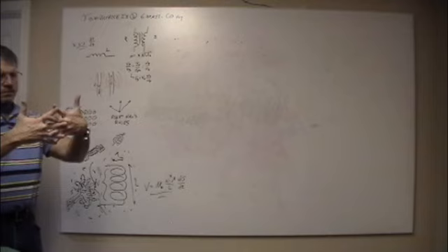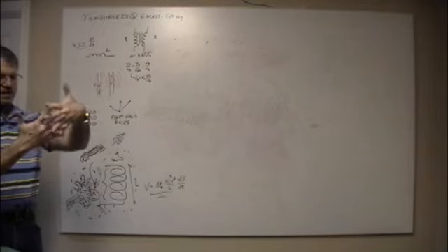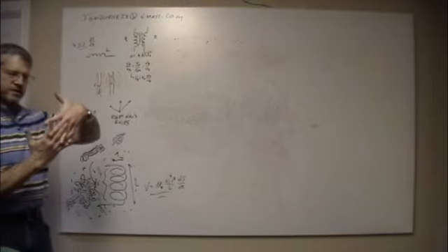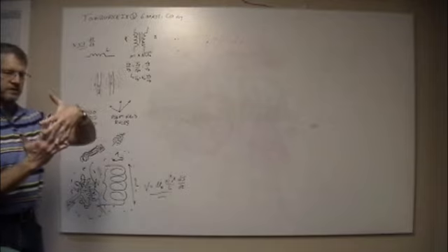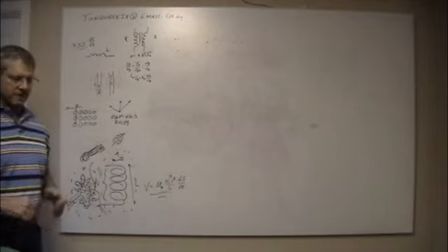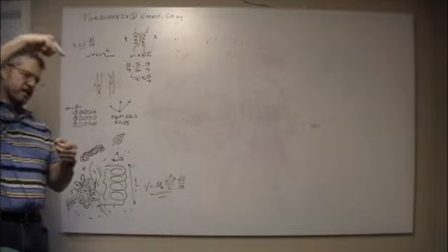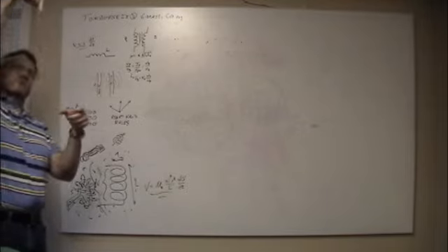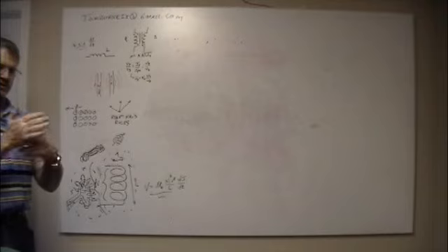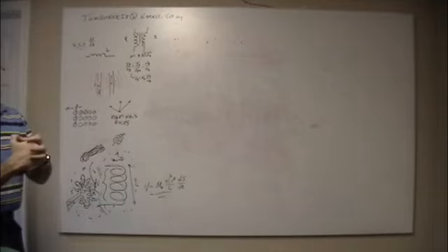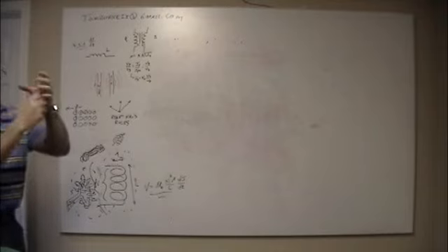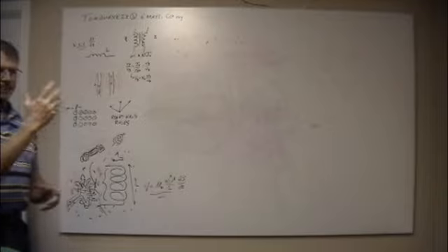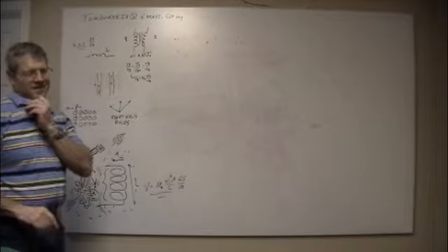The mesh makes a Faraday cage, but the little pinholes in it are leakage points for really high frequencies. So the foil's supposed to help fill in those gaps, but a foil's not that good because it lets low frequencies in through this big long spiral that goes around it. Because that is a huge hole that goes around, but it's overlapped, so all the high frequencies kind of hit. So if you set that on top of the mesh, they ground together, and it makes a more solid cage. And so you play some games there.